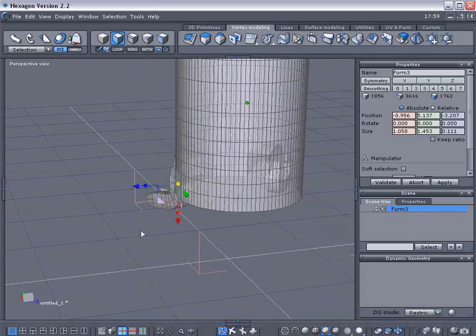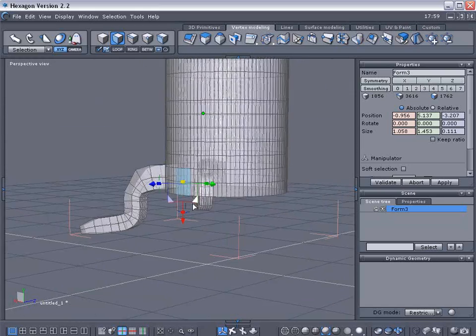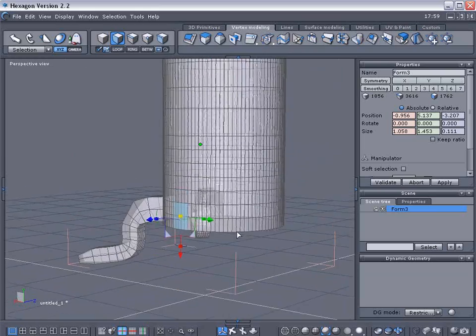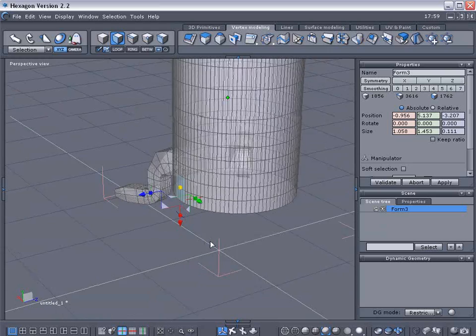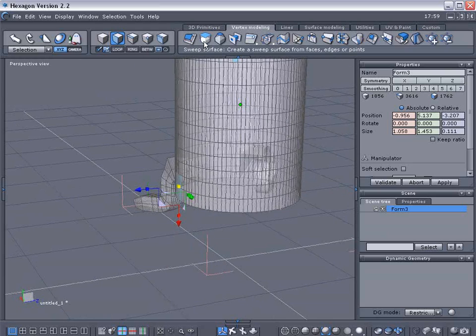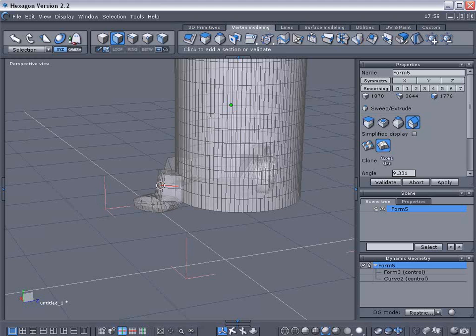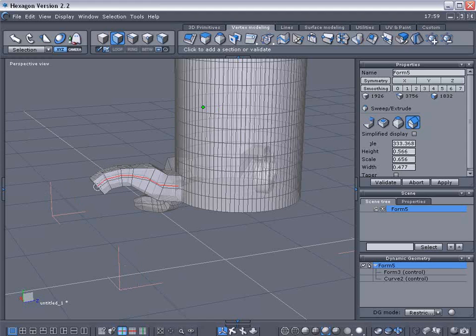And to rotate, you hold down the Alt button, and as you're holding that down, you click the left button and just drag it. And if you use the right mouse button, you can drag it up and down. So this is how we navigate around. Okay, let's go ahead and finish our legs here. And again, if you click the right mouse button here, it'll allow you to shrink or expand this. And if you click the left button, it allows you to create another segment.